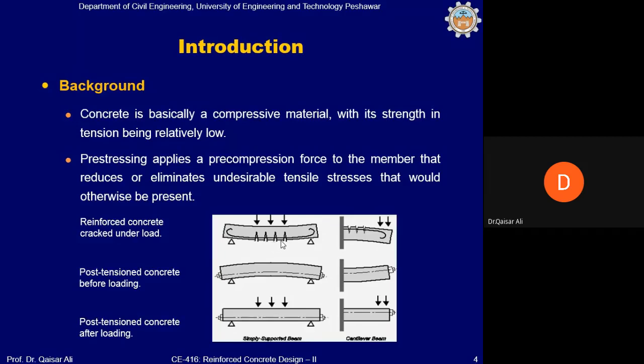However, if reinforcing bars are inserted as we do in reinforced concrete, then these cracks which appeared in plain concrete would be restrained by the reinforcing bars. The condition is that the reinforcing bar shall be properly bonded to concrete, and if this bond is perfectly intact, then the strain in concrete and reinforcing bar will be equal, and the strains will be restrained by the reinforcing steel with high modulus of elasticity and high strength.